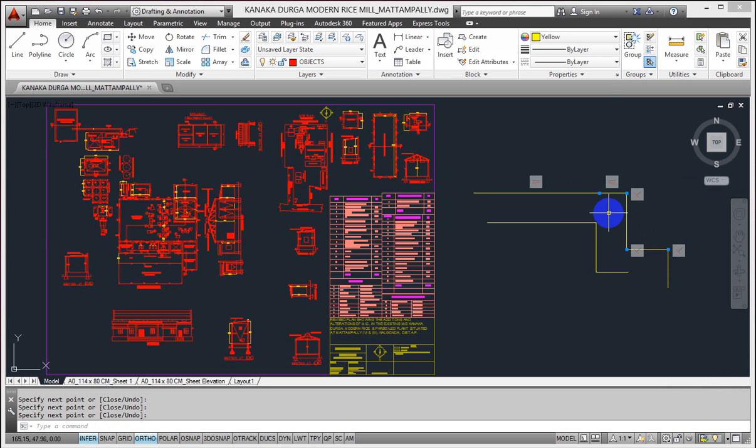If you use Infer Constraints to draw a series of lines, at the very least it will apply the coincident constraint at the end of each line segment. So it applies geometric constraints at specific pick points. Now I am removing this.